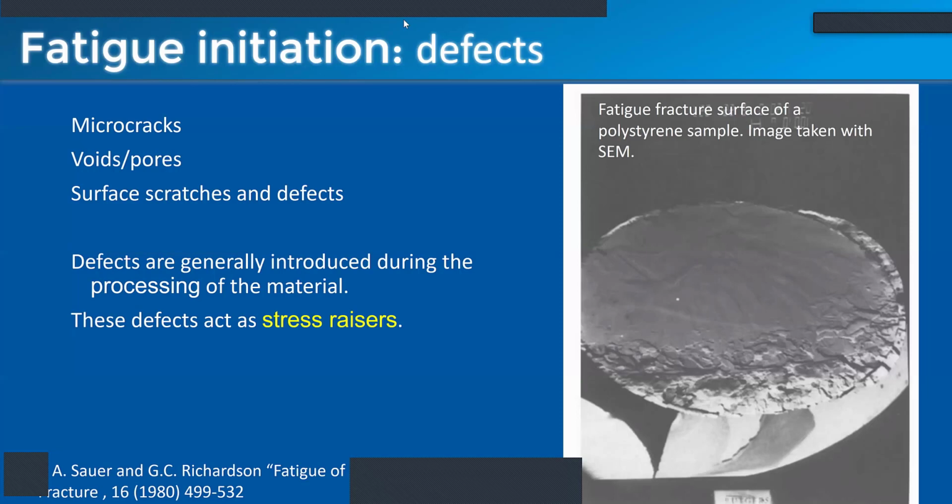So if we're starting to think about how we can predict functional properties of the material based on its structure, this is connecting the structure to function. The polymer on the bottom is bulkier. So if you had chains of polyethylene and chains of this other polymer, chains of the bulkier polymer are not going to be able to pack together as tightly as those of polyethylene. So that's going to change the mechanical properties that we see from that material.